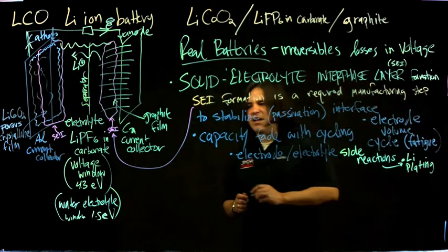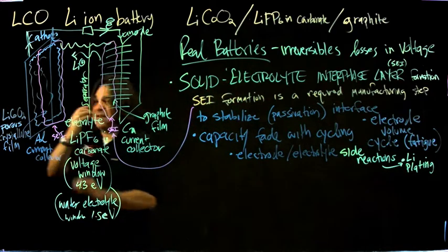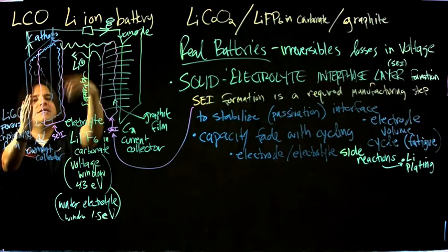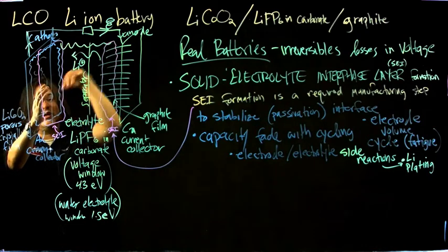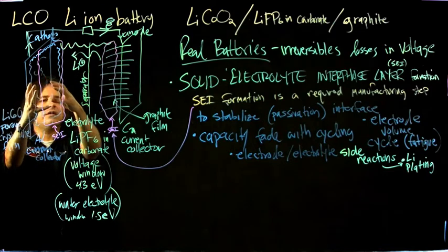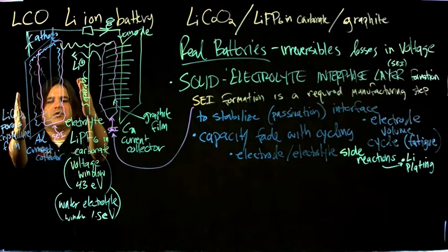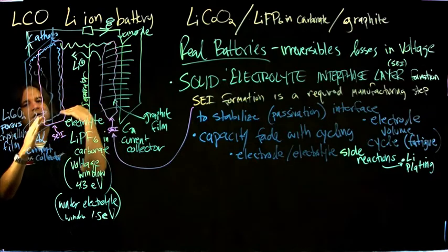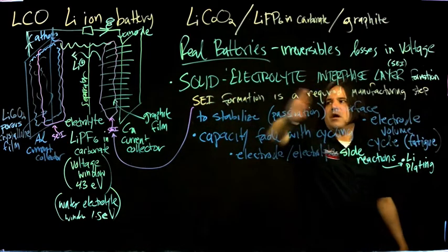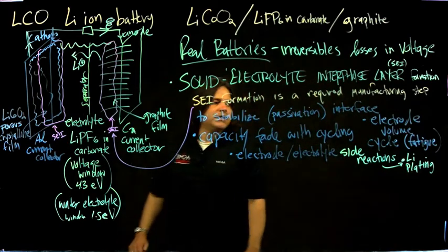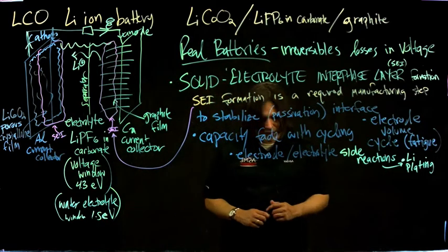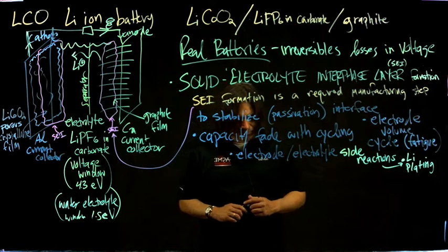That depending, if you have a lot of potential across this, in certain cases, if the electrode is too thin and you're trying to get too thick, you're trying to force these ions into the bulk of the layer. If there's a big potential drop across there, if it gets too high, you might convert lithium from the ion to a lithium metal on the aluminum. That can happen, and that can ruin the battery or decrease their performance.